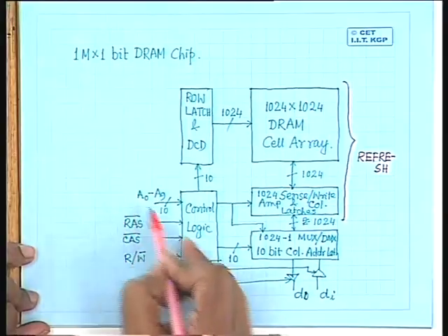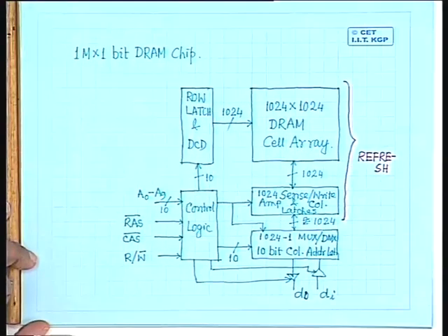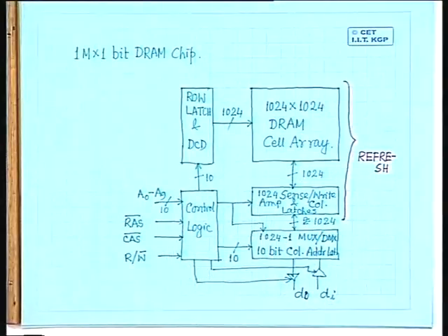Okay. So I have to have an additional controller in the DRAM unit. The diagram I have given is only for a DRAM chip. A number of such DRAM chips are to be connected together to give you a DRAM board. I'll come to that organization later. In that DRAM board, I have to have an additional control unit which will generate only these RAS signals along with the row addresses coming sequentially.